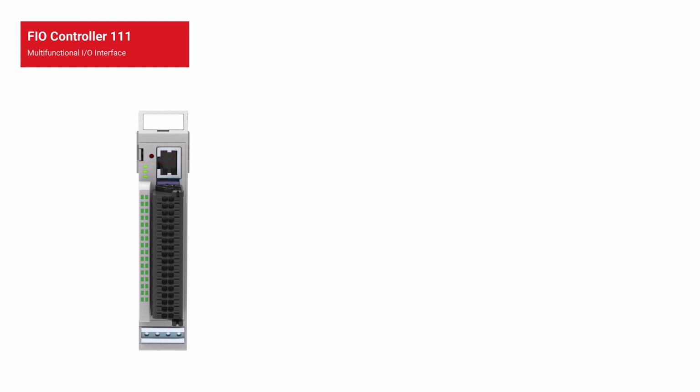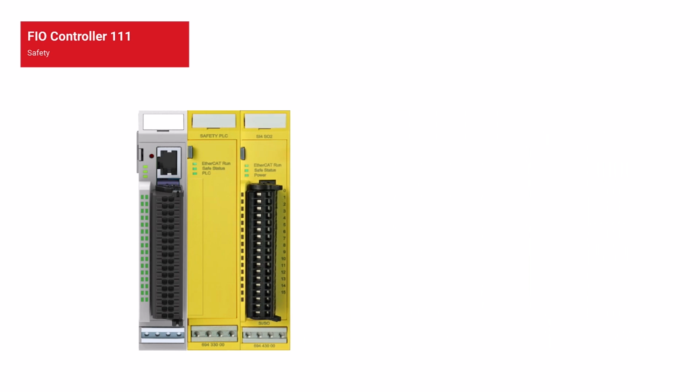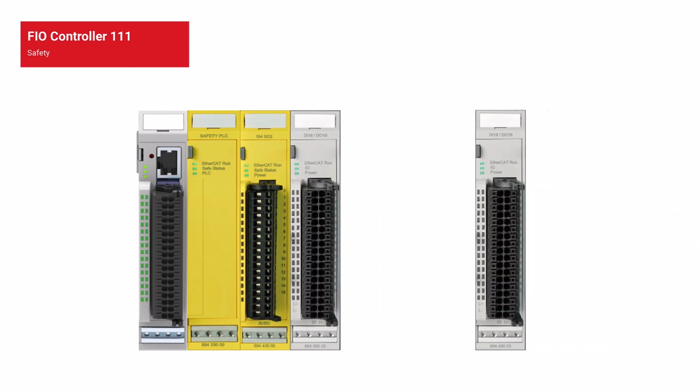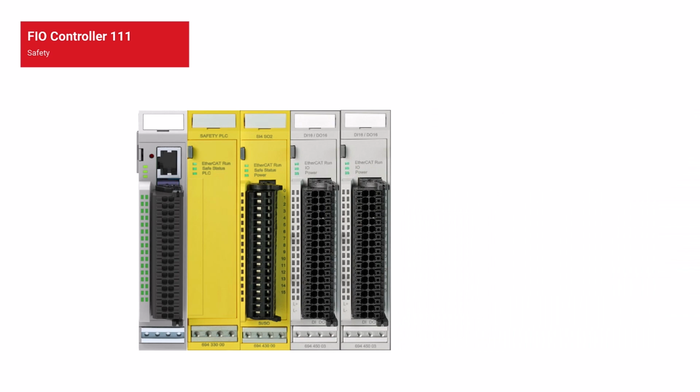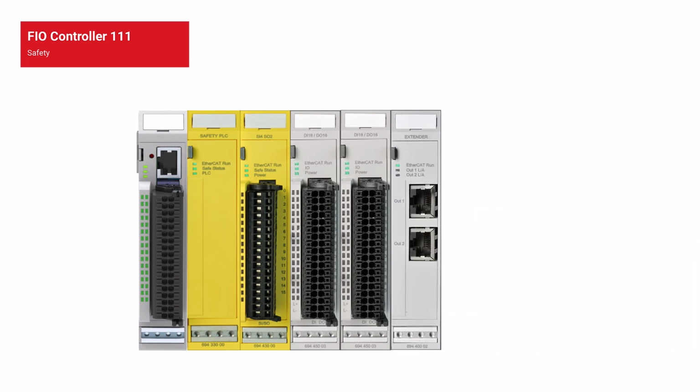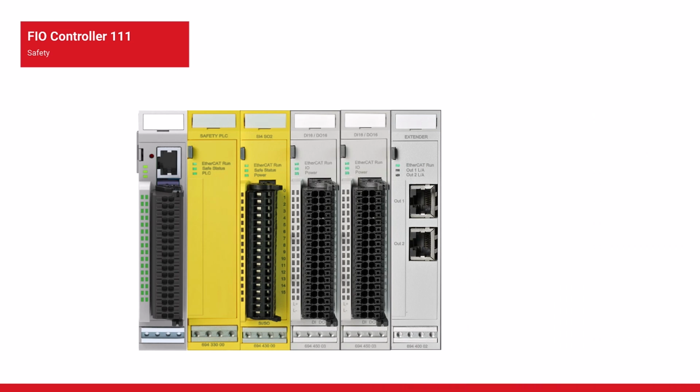And for those who care about safety, we have the good news that this controller also supports our Safety PLC and Safety I/O. So even FSoE to achieve SIL 3 is not a problem with the 111. Of course, you can also dock other EtherCAT modules from our wide-ranging FIO series to the 111 and adapt your system to your requirements. Additional EtherCAT slaves, such as drives, can be reached via our extender module.